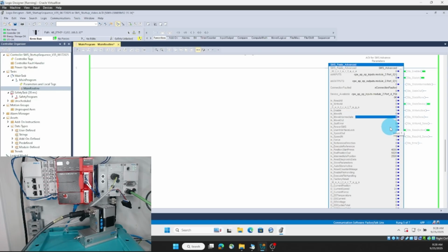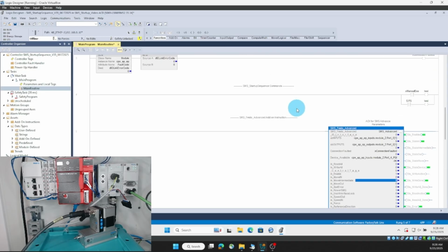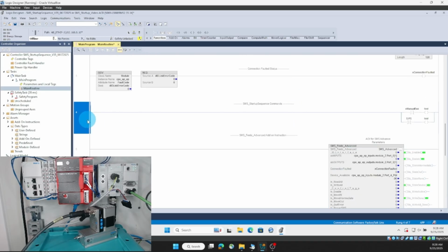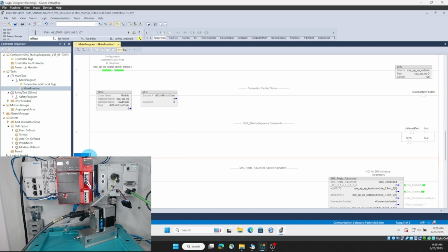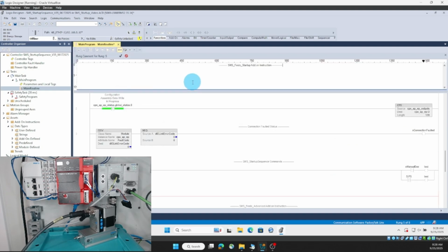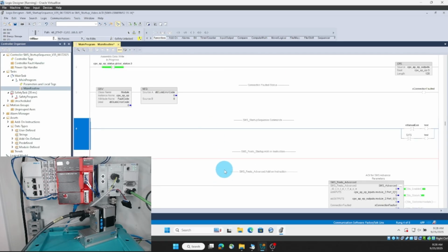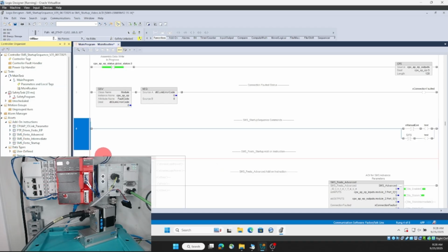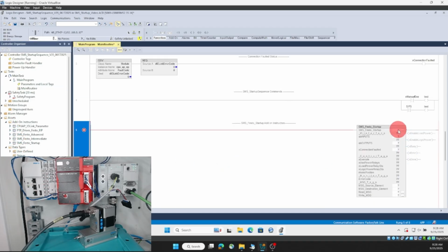To do this, I'm first going to start by clearing all these bits so that I don't get unwanted motion. I'm going to go offline. Notice that I'm going to insert this AOI right before the existing AOI. This is because they're going to share the same message instruction, and therefore I don't want the original AOI to overwrite this while it's in use. Click and drag the new AOI in. Create an instance.